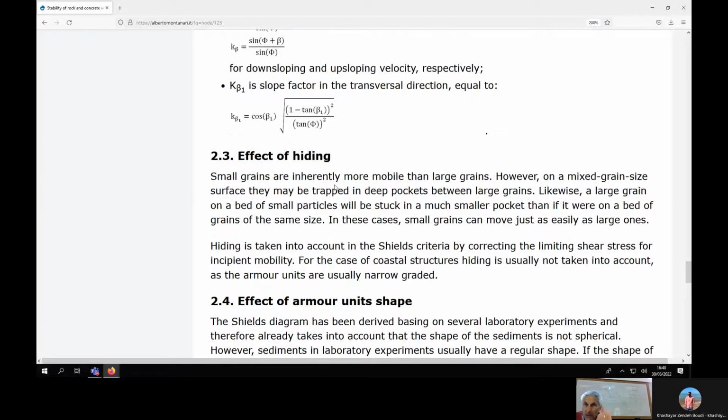You remember that in the waves you have this kind of orbital movement. This is causing, if there is an interaction with the bottom, some shear stress on the bottom, which is usually very reduced because it's a very low velocity. So in these conditions, maybe if you have currents, the shear stress of currents is higher than that. After breaking is a completely different story because you know that the transfer of energy is transformed in transfer of mass, and after breaking you have a significant velocity.